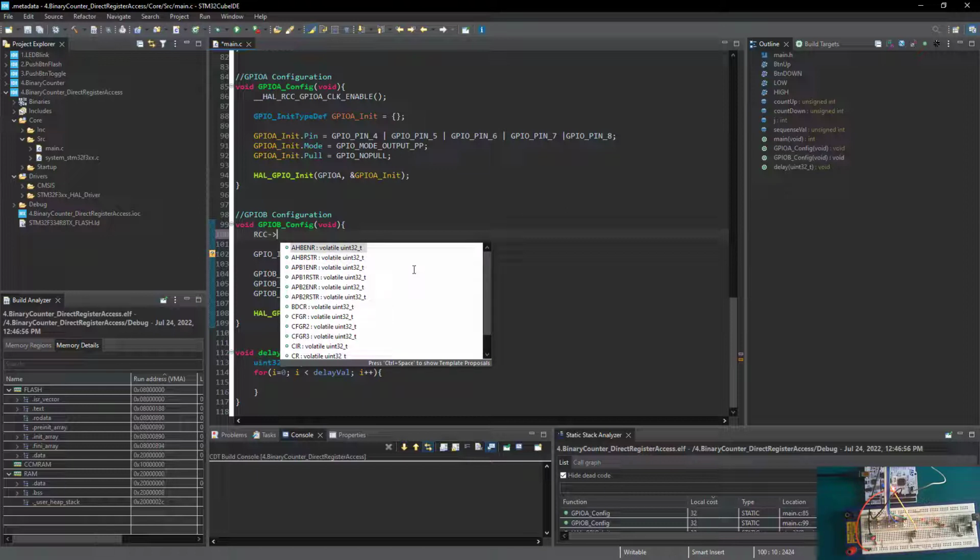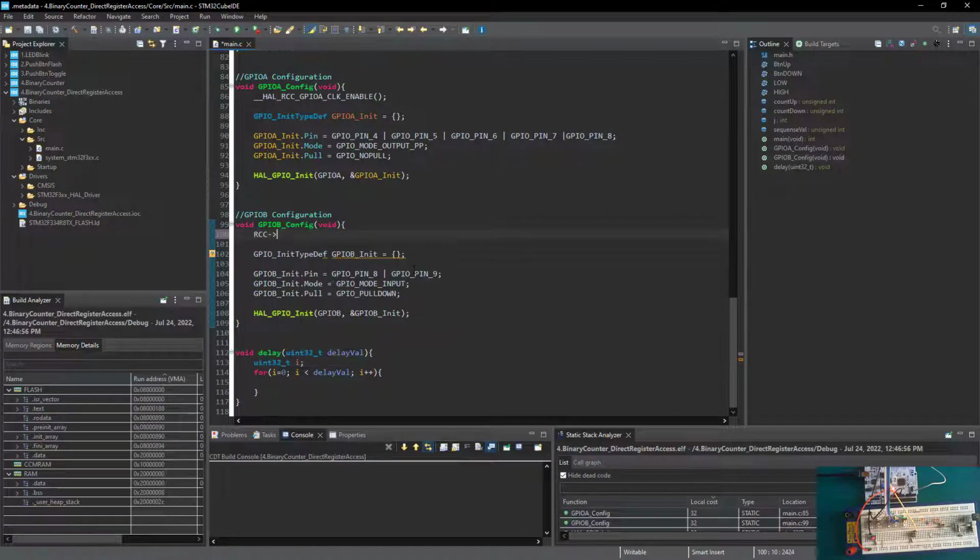You can see that it is a 32-bit unsigned integer wide. So I'm going to just click in there. Now I'm taking that. So here, it means that I'm going to access that register. So now, what am I going to do inside that register? Well, inside this register, I need to write a 1 on bit 18. Now, in order to write a 1 on bit 18, I'm going to just say equal 1 and sign long in capital letter. That's better like that. And I'm going to shift by 18 so I can write that 1 into this register.